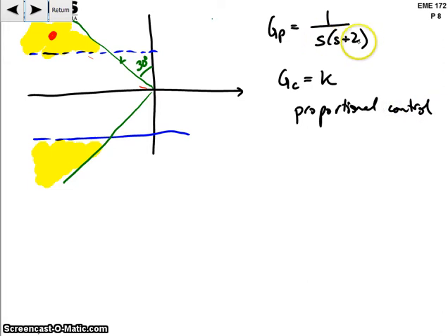Okay, so I start with the 2 open loop poles, one here at x equals 0 and one here at minus 2. And so where does the root locus lie? I'm going to draw it in red. Well, it lies on the real axis in between those 2 poles. And what happens is that for a second order system like this, they meet in the middle and they will break up and down like this. Okay, and where they intersect is at minus 1 here.